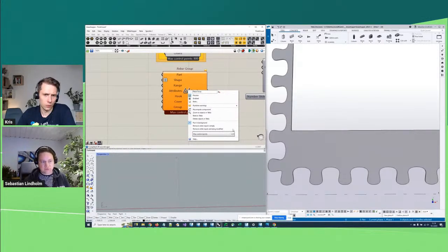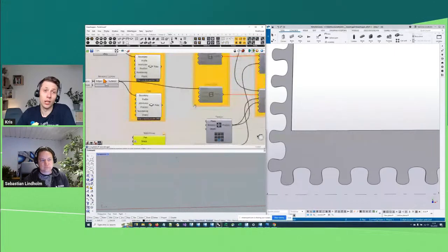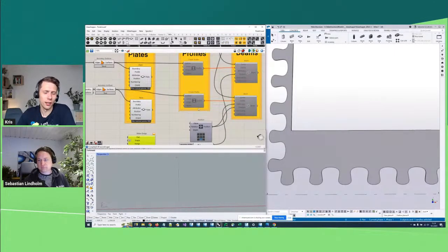You can also decrease it, of course, if you want a more crude approximation and are happy with that. Especially with the reinforcement, when you would like to have a straight shape, but the arc has a really huge radius, and you don't want it to be in the curve. In the rebar group list it will be straight. Increasing the number will help in this case, because Tekla will find the angle between each point.